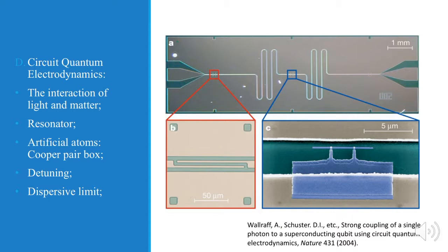Usually, we would choose to use the Cooper pair box for the circuit QED because of its large effective electric dipole moment. The resonant device used for circuit QED are superconducting coplanar waveguide microwave resonators. Coplanar waveguides, shown here in part A, consist of the signal carrying center line flanked by 2 grounded planes. The electric field is basically confined between the center conductor and the ground planes, resulting in a very small mode volume, which gives rise to a very high E field per photon.